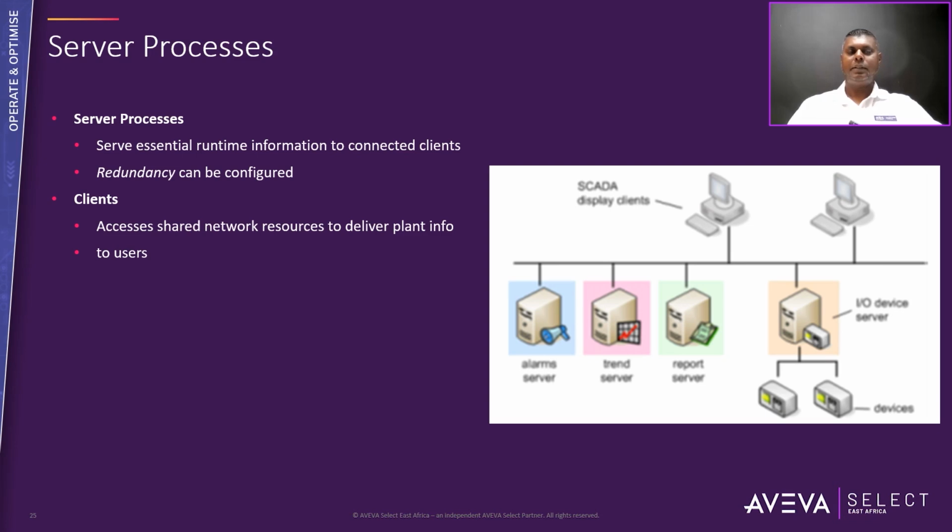Server processes. After you have configured computers, network addresses, and clusters, you can add server processes and assign them to clusters and computers. Primary and standby alarms, reports, trends, and I/O server processes can be added in Plant SCADA Studio's topology activity.